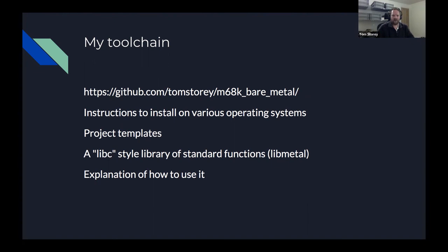And the second thing you can do is build what I've just called an application. It does almost exactly the same stuff, but it excludes the exception vector table. The idea being that you might build an operating system using the standalone project template, which will include the exception vector table. And then you might have applications that you build that run on top of that operating system. They don't need the exception vector table, so they exclude that, and that's what you could build using that.